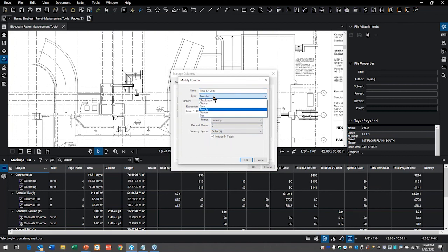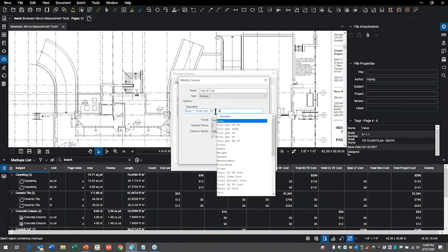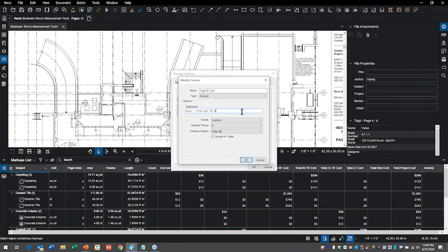And here, the drop-down underneath the title is a formula. And what you do is you simply come into the expression and you key in a letter, right? We do times and then a letter, right? So I have a function, multiply, divide, add, subtract, or some other functions, and then just put a letter in. And here are all, right, so these are your functions. Here are all of the different variables that I can use, right? I'm not actually wanting to add any more to it, but that's how you create these expressions.